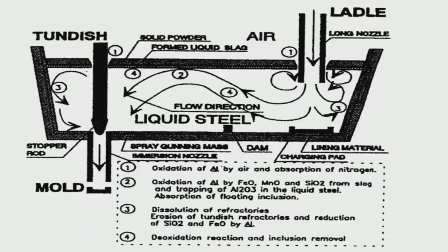Yesterday in the last session I had just started talking about what the Tundish is, what happens in the Tundish, what the issues are, and how we have to be careful during casting, so that there is no exogenous entrapment from the Tundish. So, this is liquid steel coming from the ladle. I was talking of the refractory nozzle, the refractory shroud, and we must use some argon also here, so that there is no air ingress.